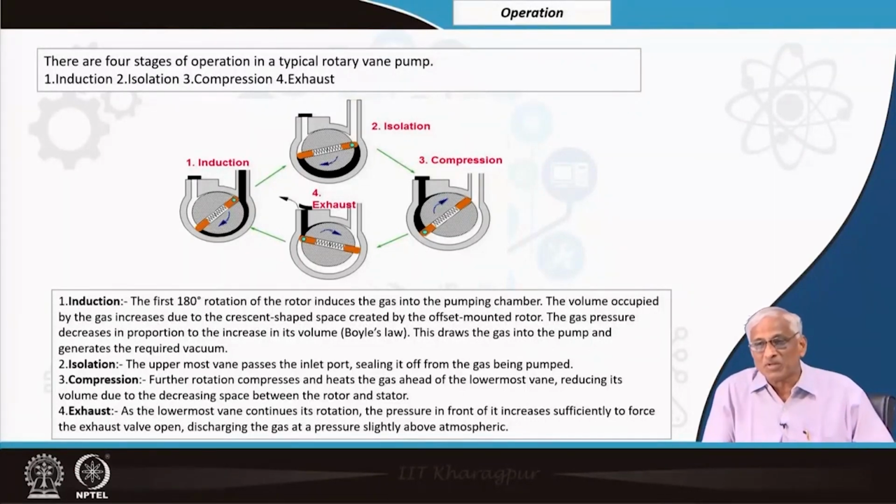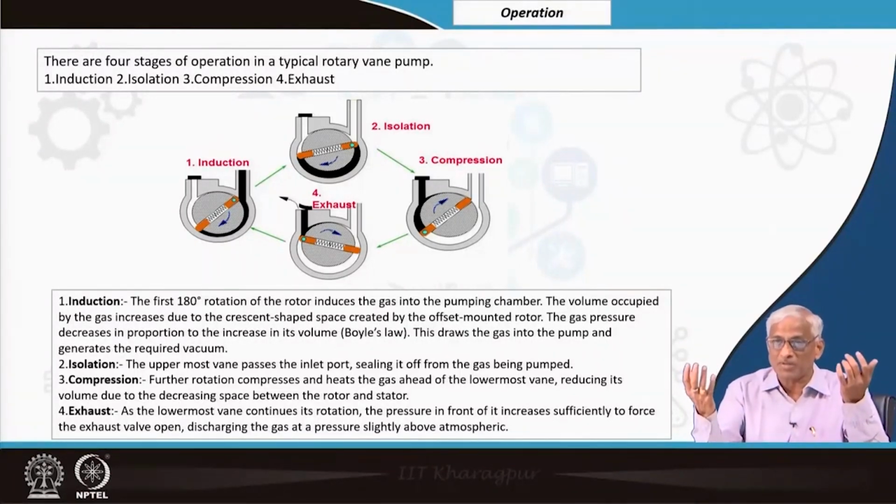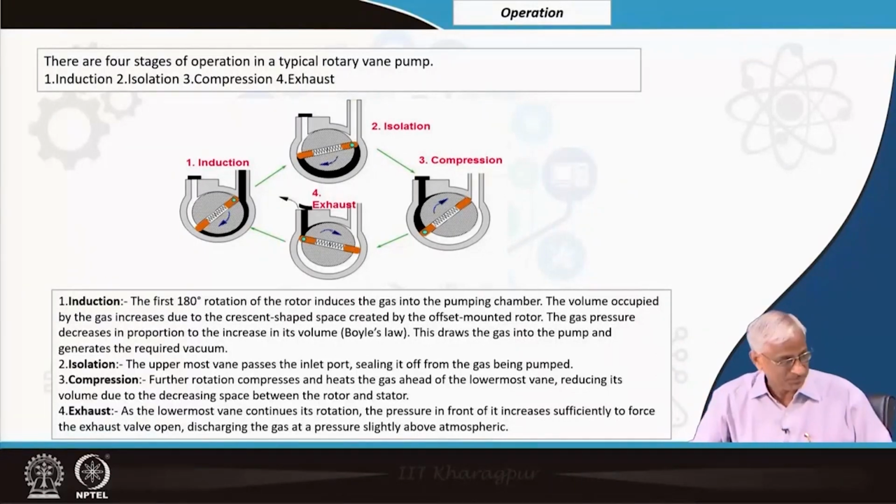So, you cannot get a vacuum better than that. So, it is customary to use 2-stage series connected pumps. But if your vacuum level itself is 100 torr, you do not require 2 stages. If you are connecting 2 pumps in series, instead you connect them in parallel, both of them will be sucking the higher pressure side, 10 torr operating pressure, and pumping speed will be more.